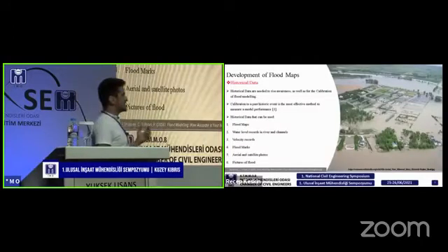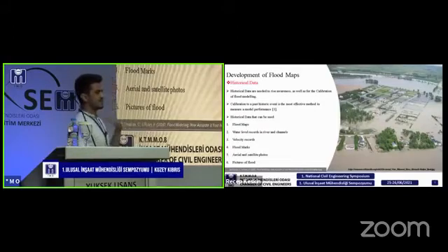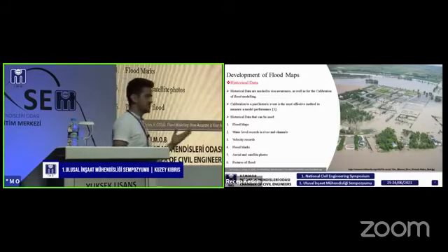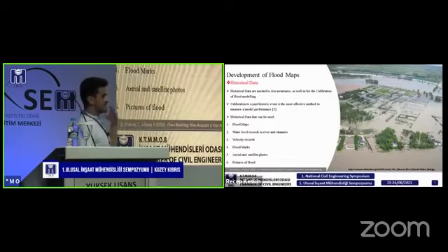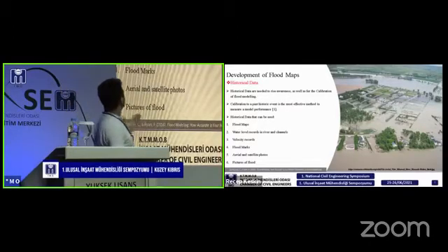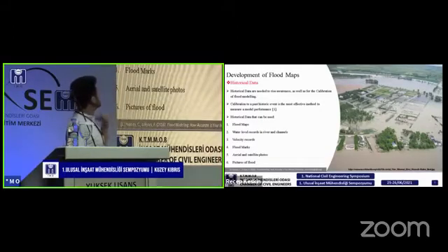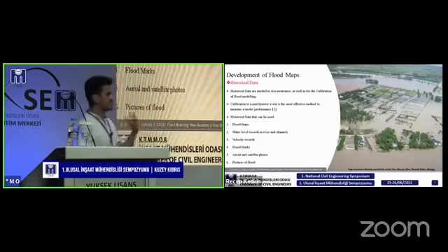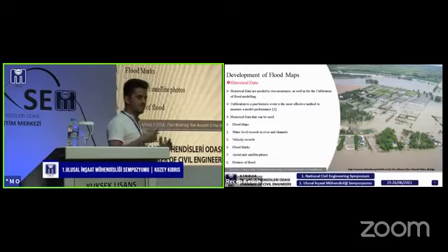Another important data set that we need is historical data, like what kind of floods happened before, as Hassan Hoja expressed. We have to have the historical data. Historical data are needed to raise awareness as well as for the calibration of flood modeling. And calibration to past historic events is the most effective method for us to make sure that the model that we develop is performing well.